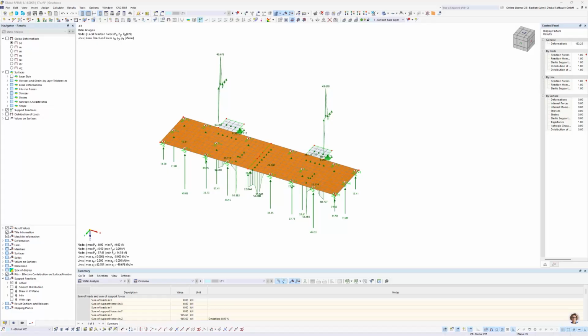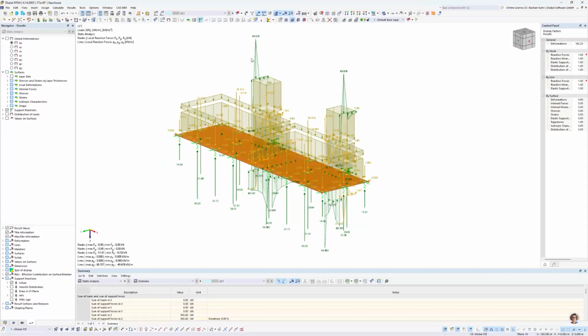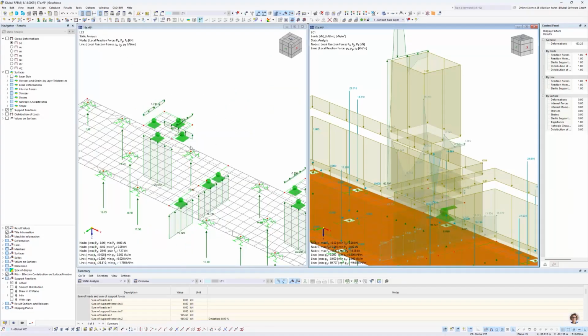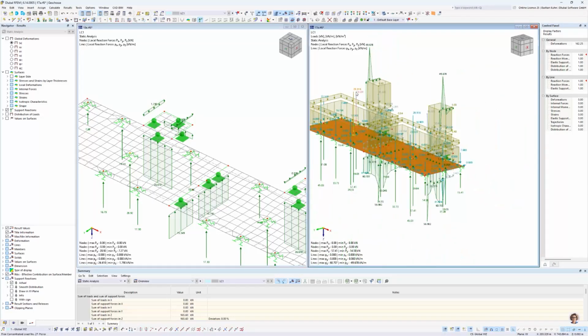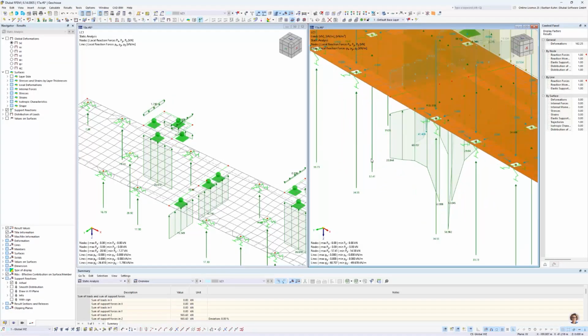So, and now you see, I have the result. And when we look at the forces, you have here the 28.9, which is maybe, when we tile it in this way, you see here 28.9. So it's taking the force from this node and applying it on this. And then, of course, together with the other load that I have in here, it's giving me this 57, which is also the normal force. So that's a way to also regard 3D effects in 2D.